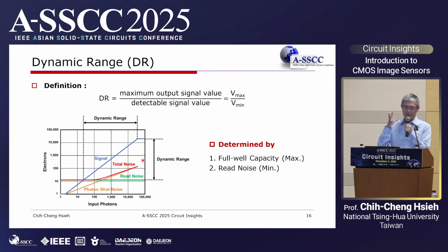So when you receive 100 photons, if you check the photon number over a long time, the number will not stay constant even under constant illumination. So basically the photon number will fluctuate, and that will introduce some photon-generated shot noise. And basically it will be equal to the square root of your input photons. So that's why we will get another curve here.